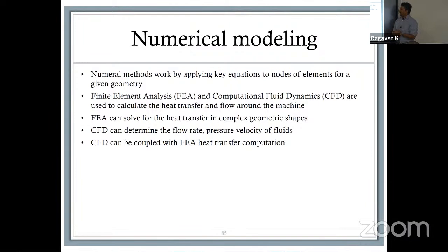For this specific one, I think it was not taxed as much. It was a relatively larger motor with a bigger OD. The fill factor was not quite so tight. So I think this one did not go beyond 80 or 90 degrees C. So for water cool, it was more than plenty for what we were trying to accomplish. But I have to look back at the max temperature. I think I have a table somewhere. I don't know if I put that in here or not. I can always tell you offline what that number was.